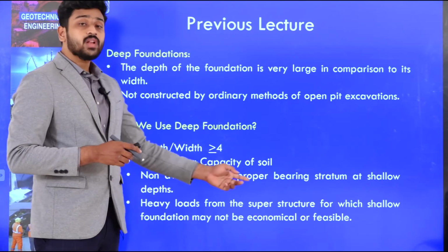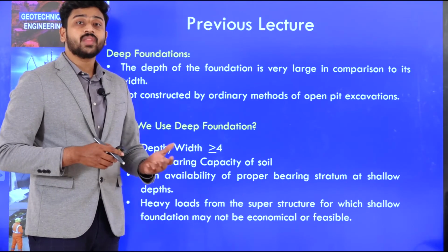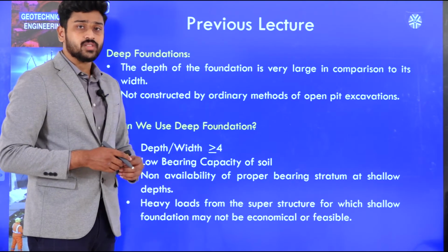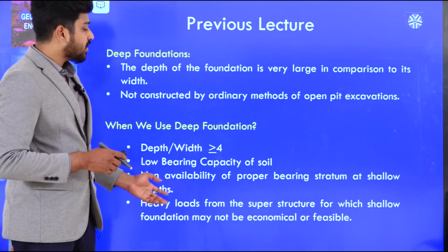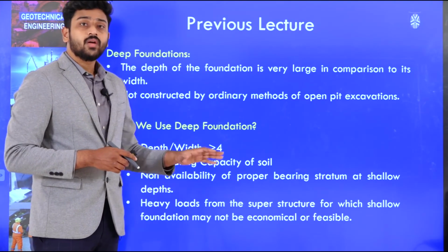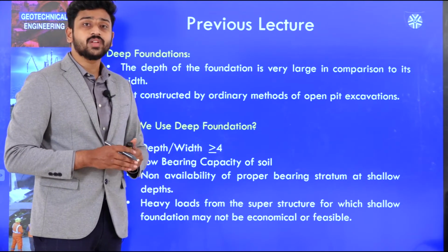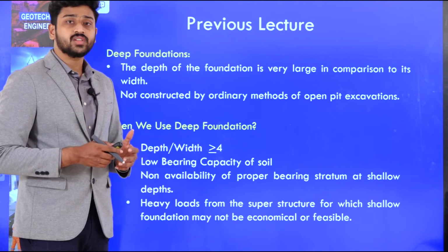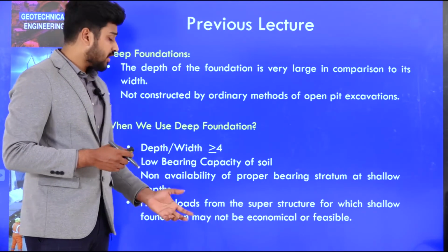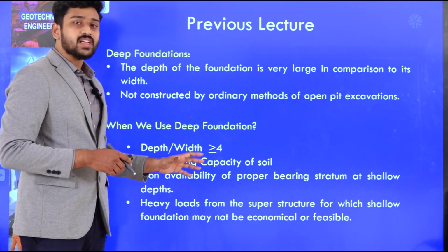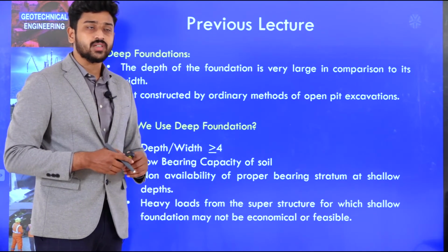When there is non availability of a proper stratum along the shallow depths, then also we go for deep foundations. And when heavy loads are coming from the superstructure onto the foundation, and it is not economically feasible to construct a shallow foundation to bear such large loads, then also we may go for a deep foundation. Okay. So, in any of these cases we may prefer the deep foundation.